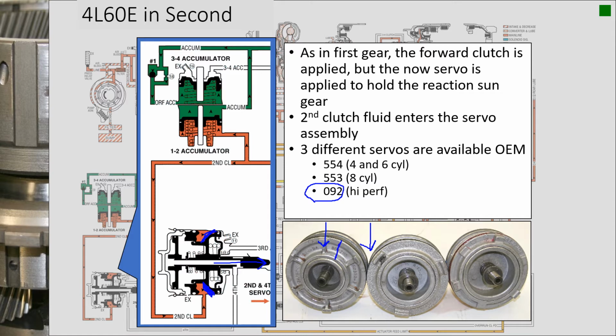So the surface area is going to be from this divider piston that I see right here. That is equivalent to the surface area that the piston has, because the fluid is going to go between the outer seal and the inner seal. And you look, that's pretty much that dimension right there.